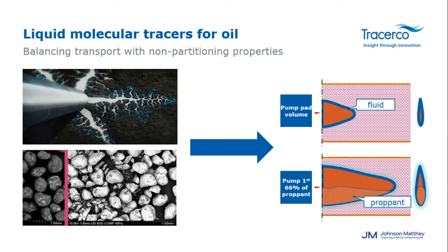Just as a reminder, the tracer deployment and timing across the stimulation can affect results. Liquid, water, oil, and gas tracers will provide quantitative production and can be designed to provide phase-specific data for desired objectives. Particulate tracers will only provide qualitative data due to the number of multiple complicating factors that cannot be resolved.